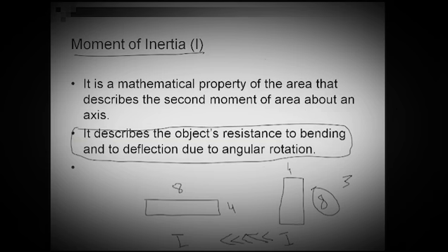And if an object has a huge moment of inertia, right away you would select that for your beam situation, for it to resist deflection and flexure in a beam bending situation. Make sense? So not so scary now after all, is it? An equation, bh cubed over 12. You add it to your formula sheet and you go on.